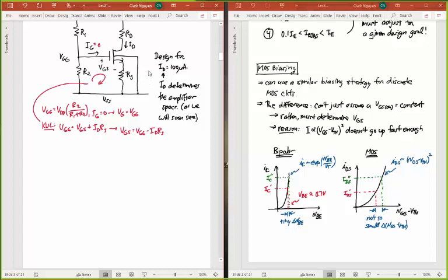And so I know that the drain current for an MOS transistor is just 1/2 mu n times Cox times W over L times whatever the VGS is minus whatever the threshold voltage is, squared. And then there's this 1 plus lambda times VDS with that as well.